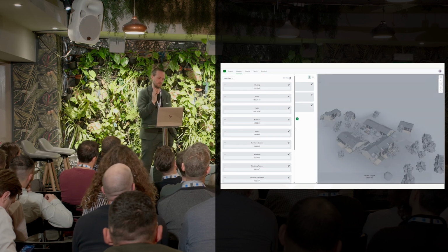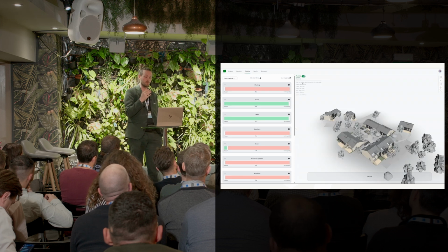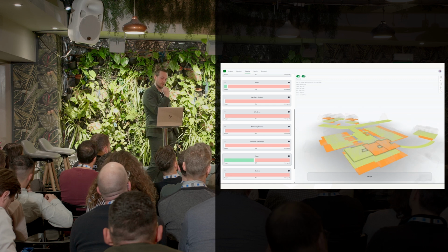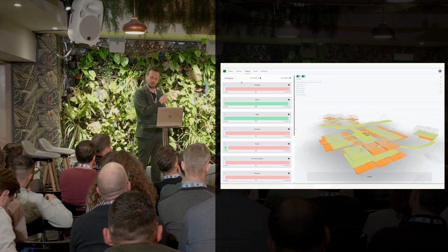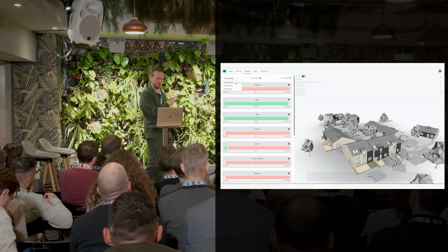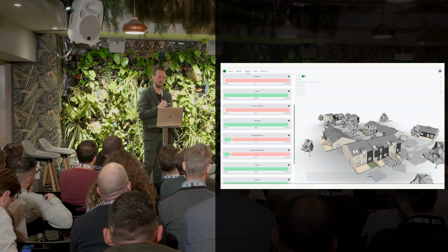So it doesn't matter if they did something weird and put things in modules that shouldn't be in modules in Revit. We can just take our mapping from phase 2. You can see that, okay, we're missing some parts. Now, I've made it TV chef style, so I already prepared it. So we have our phase 3. Yep, everything that needs to be filled in is filled in.